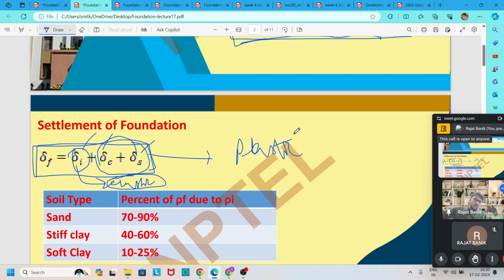It occurs when, we see that below the foundation the pressure may vary like this. Immediately, meaning at the time of construction of the foundation, the foundation soil may get settled immediately after constructing the foundation, and this pressure lies within the elastic zone, and this settlement is called elastic settlement. After a period of time, the pressure increases gradually and the soil may fail